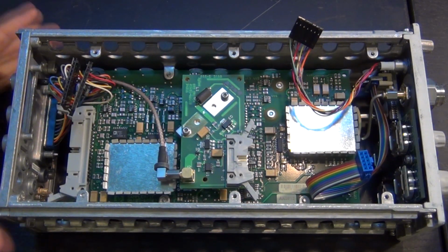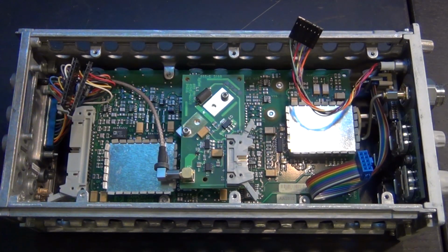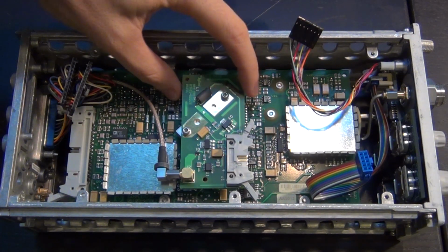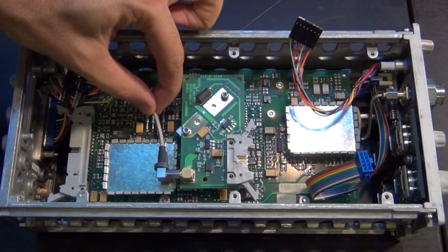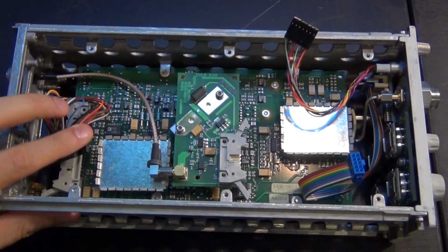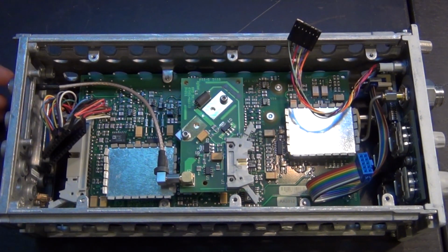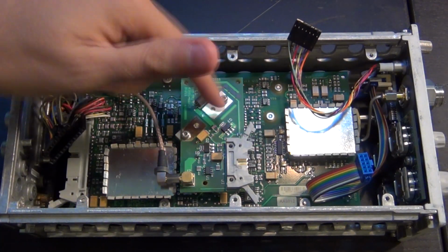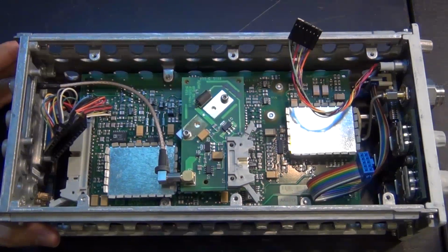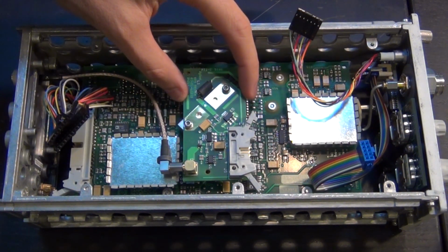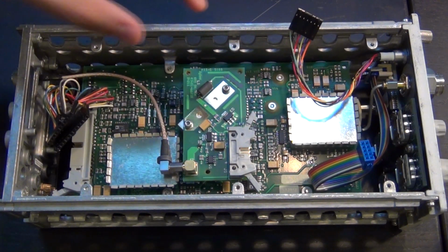And here is the other side of that board, and here we can see, of course, everything else that I was talking about. This is the back of the impulse generator, the pulse shaping impulse generator, and this is the input to it. And this obviously is the only analog RF input that's coming from the mainframe. That was the connector I was asking you if you could guess what it is, and that goes into here. So this is our trigger signal going into this module, which becomes an impulse train, very narrow impulses for the high bandwidth that's required. So this whole module here is responsible for performing just that one task.